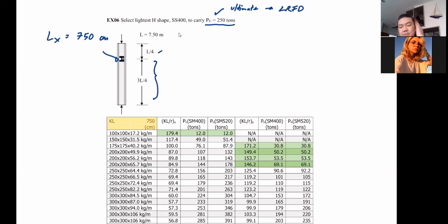So we may have mentioned this before in class that it is, of course, the most optimum idea to have the bracing in the middle, because if you face a case like this, you now know that this part is going to buckle first because it's longer. So why have the brace at that point, right? But in real life, you may not be able to choose where you can brace your structure due to some architectural demands or some obstacles or anything. So that happens.